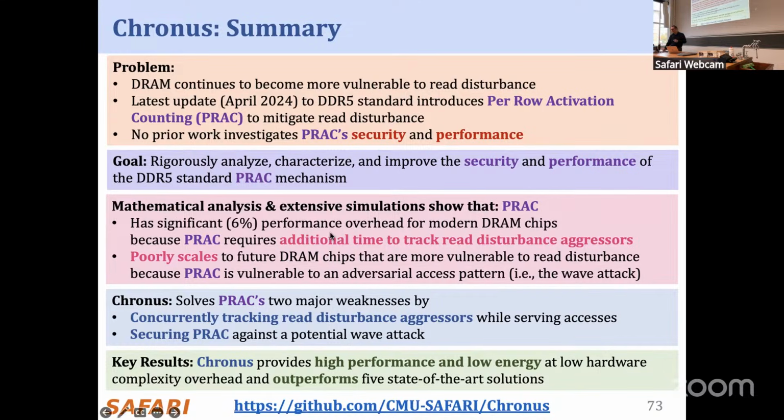Again, you can read the paper, but you can see that there's a significant performance overhead for existing chips, like 6%, because you need additional time to track read disturbance aggressors. That's in normal operation, because they always increase the precharge latency. And if you have a future chip, it's vulnerable, so you need to be careful about what you do. This paper proposed some solutions, but I'm not going to talk about them. You can read this paper, and maybe it will be presented as part of the cutting-edge research. We show that this outperforms existing solutions.